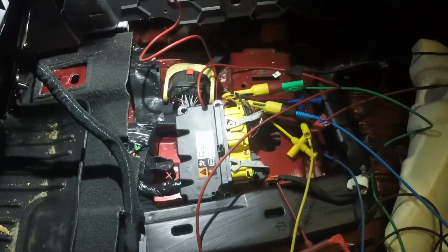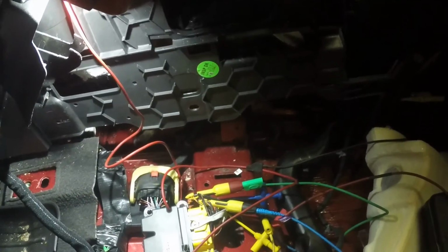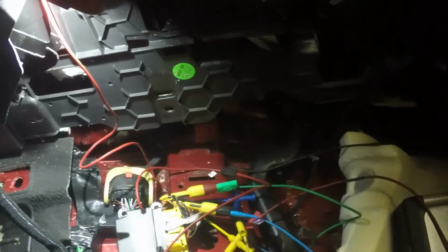I decided that I was going to pull it up so I could get at the connectors and the pins easier. You can also see right here where they've repaired some wiring on this thing. And yeah, so I think the next thing we're going to do is scope from here out to the actual crash sensor on the left front.